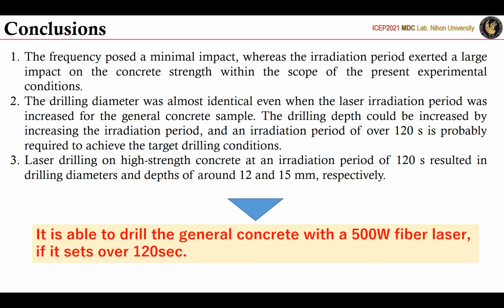Third, laser drilling on high-strength concrete at an irradiation period of 120 seconds resulted in drilling diameters and depths of around 12 and 15 millimeters, respectively.